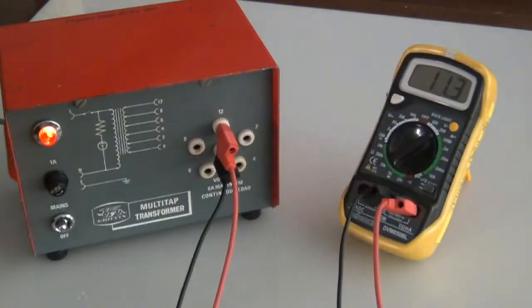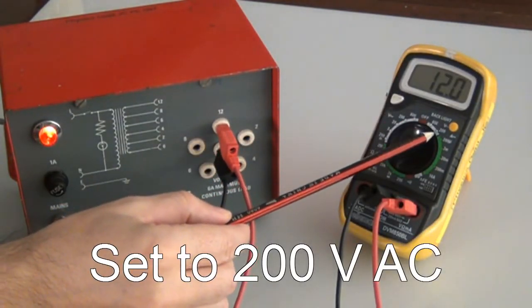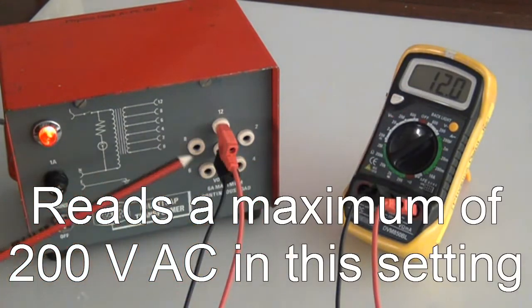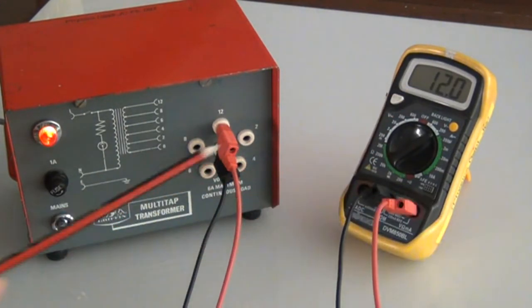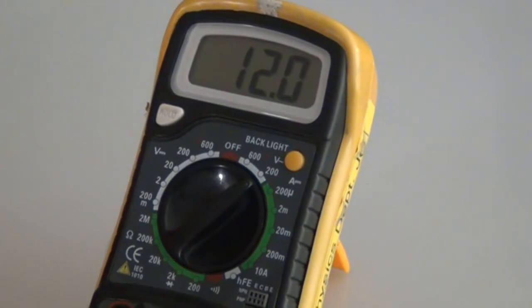and we rotate the selector switch to a suitable voltage. We have chosen the 200 volt AC. This means that it can measure up to a maximum of 200 volts AC in this setting. But our output is 12 volts, so this will read 12 volts on the display.